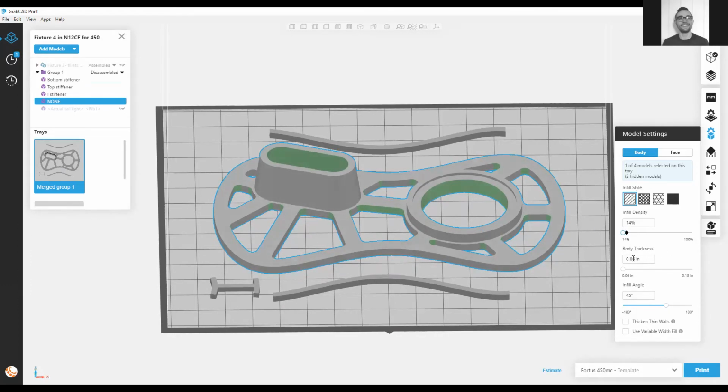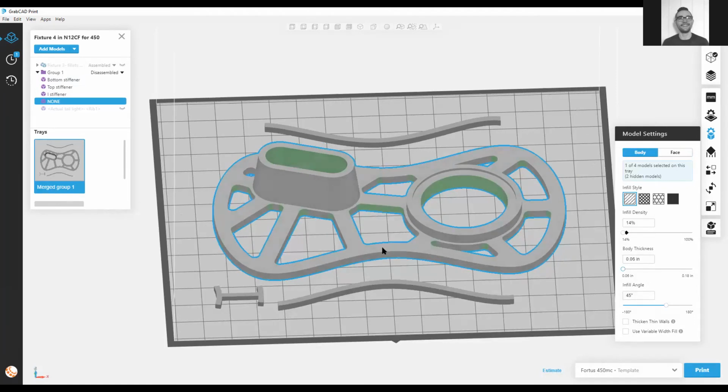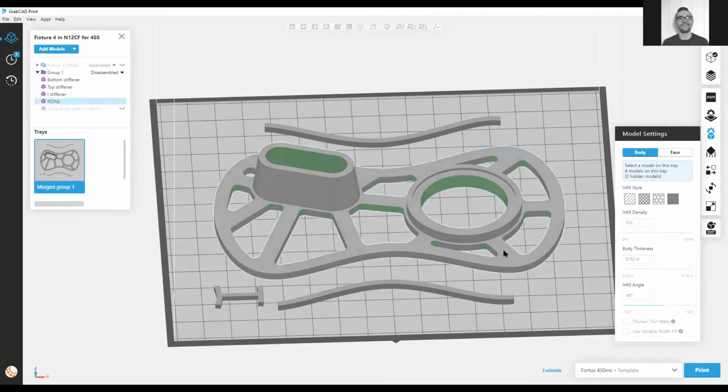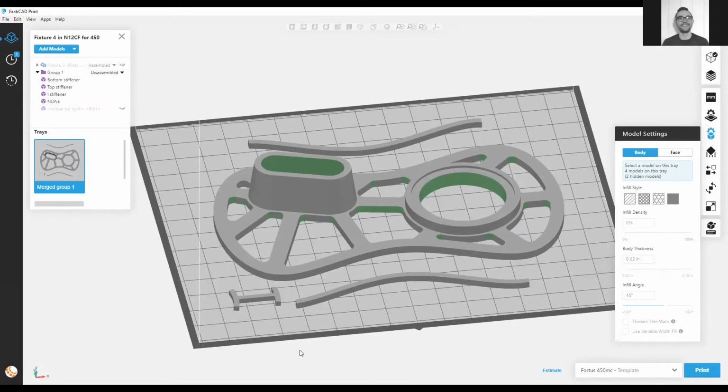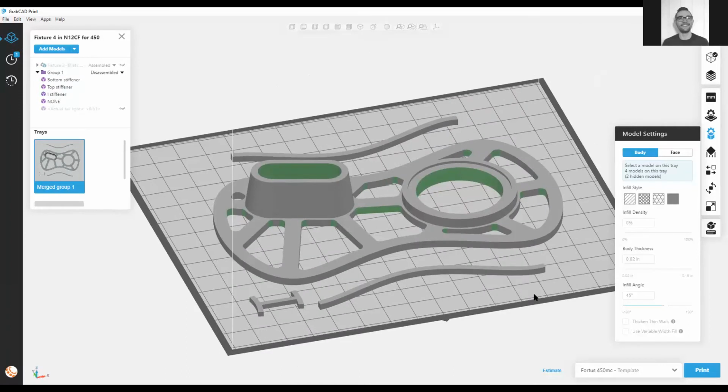Body thickness, this is the contour, or the number of contours around, for those Insight users that are familiar with that terminology. It can be adjusted. Right now we're at the default body thickness, which is an outer contour plus 2 inner contours, so 60 total. Again, we can thicken that up if we want to, but because we've selectively reinforced all of these faces, there's no need to globally reinforce the rest. There's no holes on this part where we'd want to make self-supporting or apply an insert, so we're not going to see that performed here, but it is another powerful feature within the software.